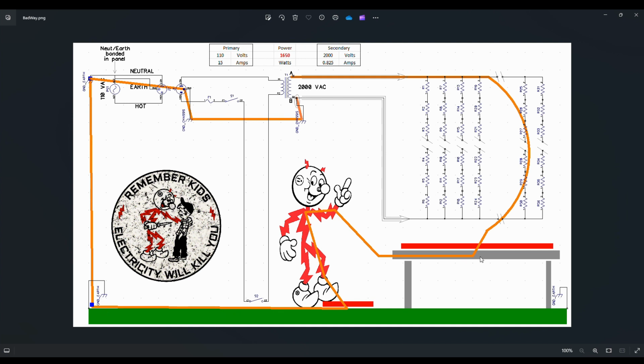Should, for whatever reason, this clamp, this wire, this conductor have any issue, it doesn't have to be a total failure, it could be some partial failure that makes it slightly less than the most attractive pathway back for the electrons to reach point B here. So by leaving that ground in place, you've left the door open for all these kinds of crazy accidents to happen.